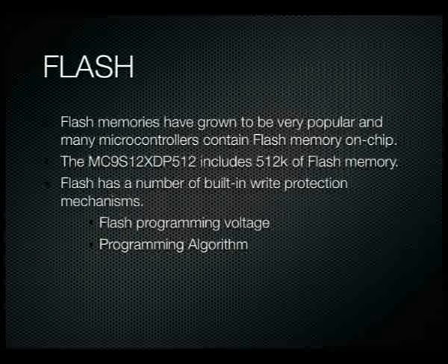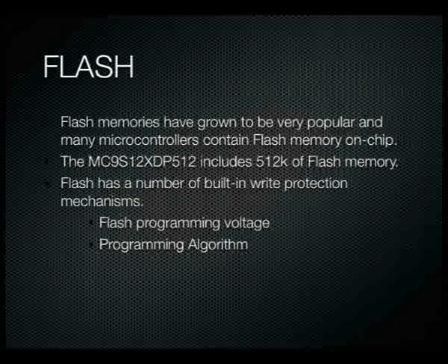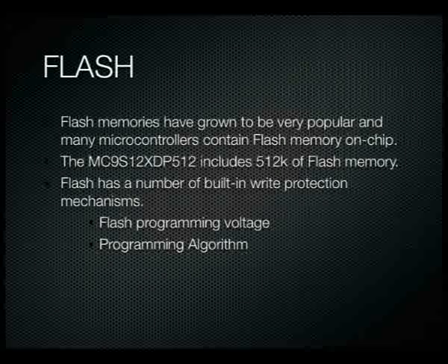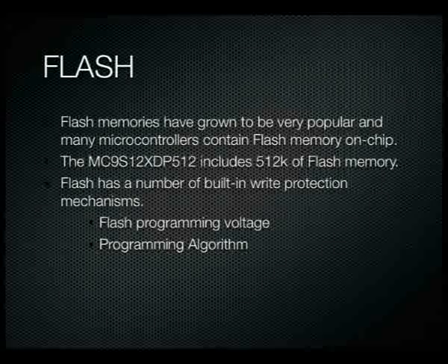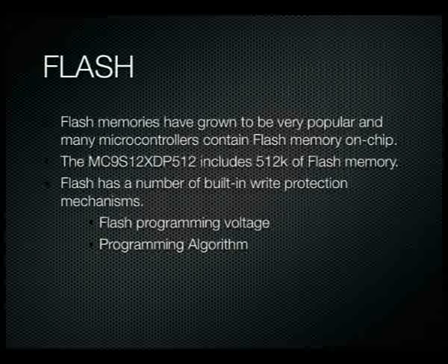But people can handle this. Flash has become extremely popular. You can get flash drives, you get flash in any sort of device these days. Your iPods contain a considerable amount of flash. Flash has become very popular, it's very cheap, and it's very cost effective, so people usually put up with this block-wide erasability thing just because it's cost effective. Many microcontrollers also contain a hell of a lot of flash memory on chip.